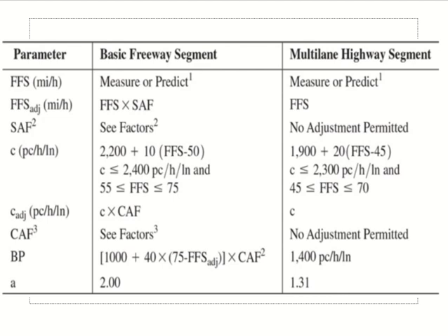Now they are using adjusted free flow speed. And this is again capacity adjustment factors. We discussed adjustments. They are for 4 conditions: weather, incident, work zone, driver population. Anything mentioned in the question about weather? Anything mentioned about work zone? Anything mentioned about driver population? No? And anything mentioned about incident? Anything mentioned about traffic? Yes.